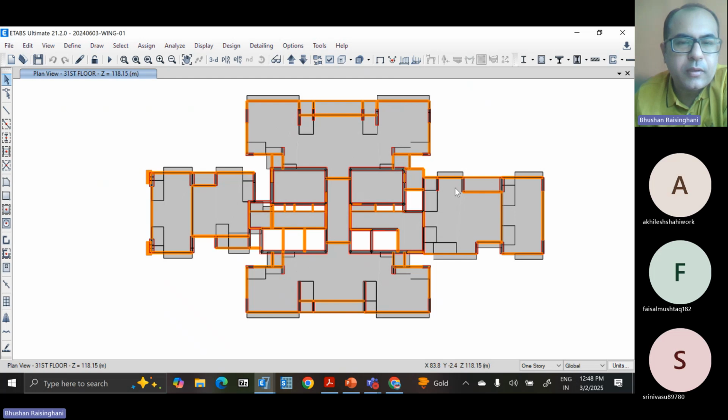So this plus arrangement of the building you will see mostly everywhere in Mumbai, mostly I-shaped buildings. And it gives a very strong core at the center, and perimeter is very well connected by the columns. So they take the lateral forces. Inside all are the gravity columns.